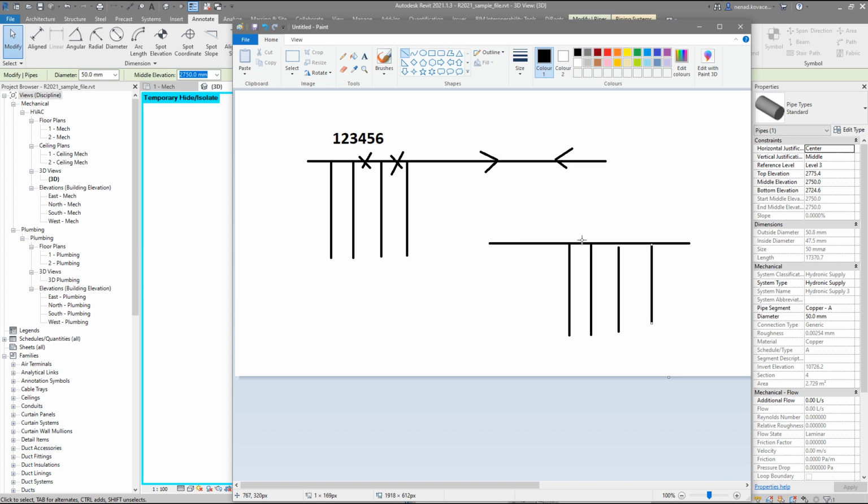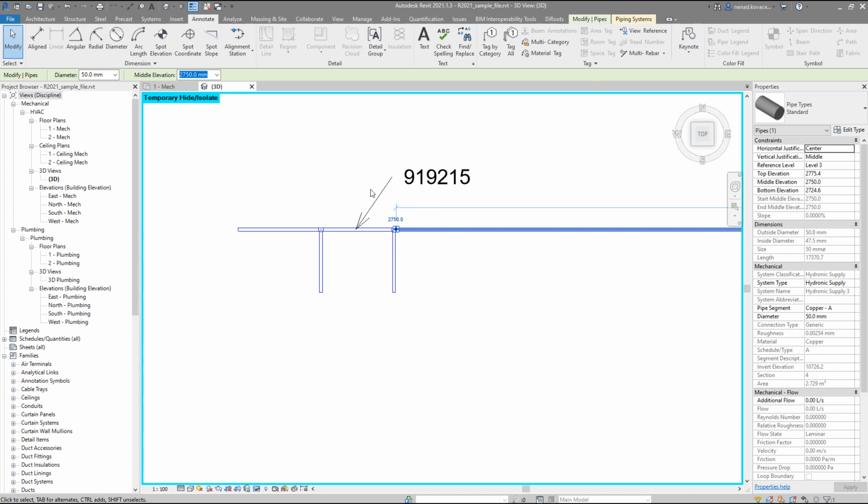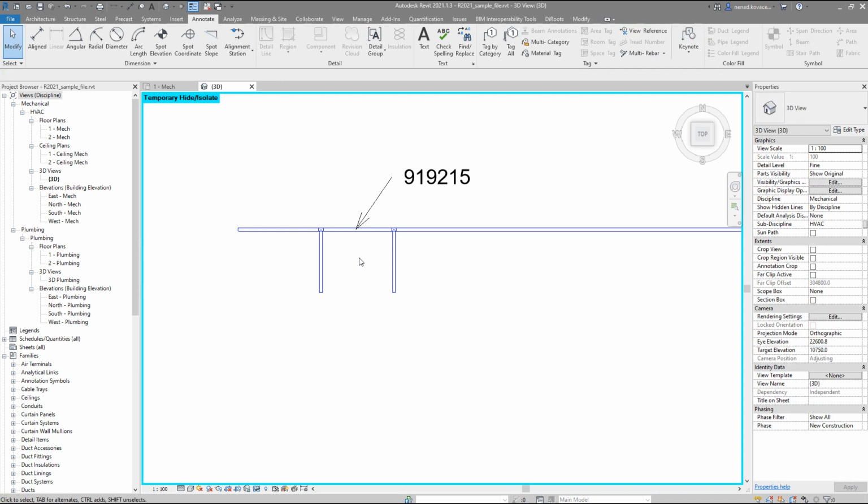I tried to find some logic for how Revit actually assigns those IDs. Unfortunately, in the end, we just agreed that we cannot rely on that, and I tried to find some other solution in order to force Dynamo to create those connections anyway.